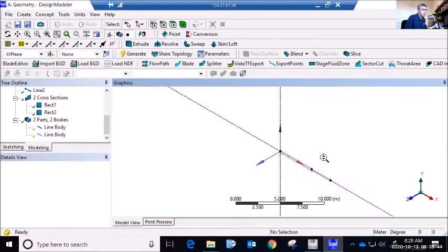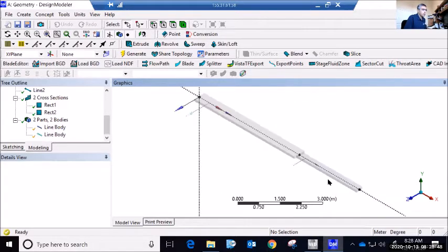You see the way that these are oriented. They are oriented more like a bookshelf, where the base is wider than the height, simply because when I defined my cross section, it was defined in the XY plane, Y being the height. By default, ANSYS aligns the Y axis in the Z direction. So the Y axis is aligned in the Z direction.